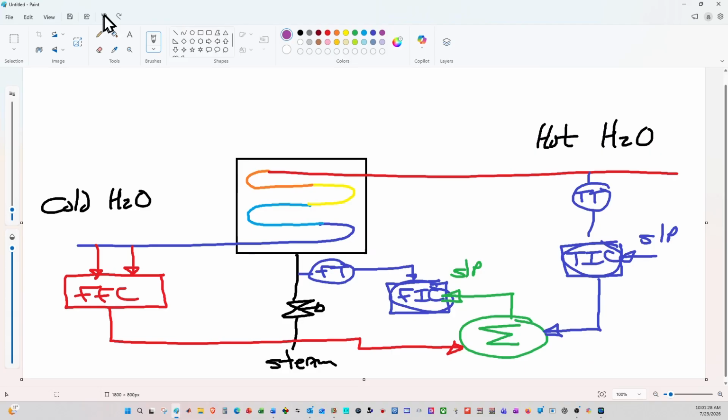We now end up getting the best of both worlds, and that will in many cases give us greater stability out in the field. Now I'm going to bring up a simulator, the simulator that I always use, and we will show you how all of this fits together quite nicely. You will see the flow controller, which will work on the steam, and you will see the temperature controller, and you're going to see the combined effort of the feed forward and the feedback.